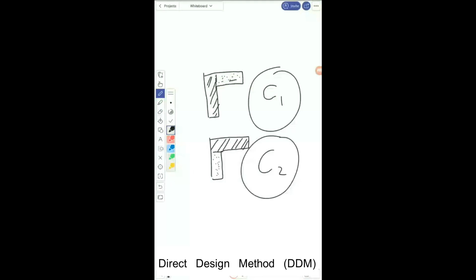In the same way, if I have a rectangular beam like this one, I will calculate a torsional constant first by making a line here, making this one rectangular component and this one the second rectangular component. The other option, I will make the same shape beam here and make a line this way. So this will be my first rectangular component and this will be my second. I'm going to calculate C1 for this situation, then C2 for this one. Out of C1 and C2, the largest value will be selected.